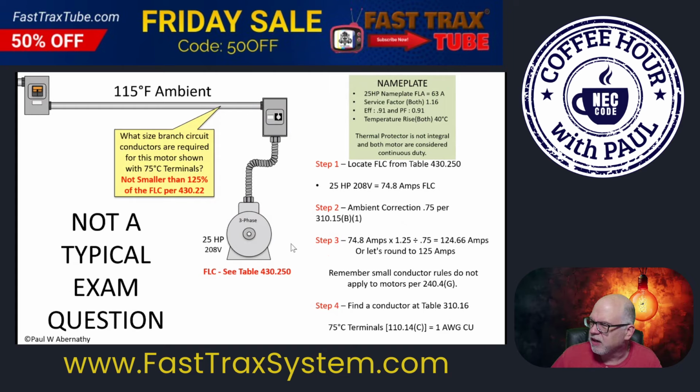But ours was obviously a little different because we had the 115 degrees Fahrenheit thrown in. So we can't be smaller than 125% of the FLC. Same thing applies. The only difference here is 74.8 amps times 1.25 divided by 0.75 is 124.66. We're going to round that to 125. And we go to the 75-degree column, and we have to find a conductor that can handle the 125 amps. And of course, our 1 gauge is good for 130.